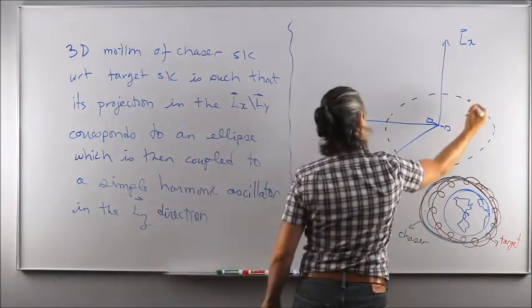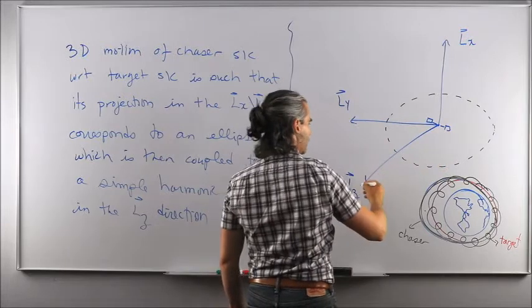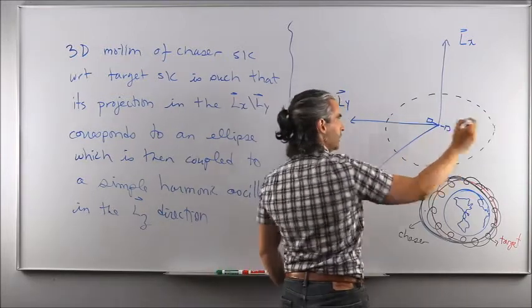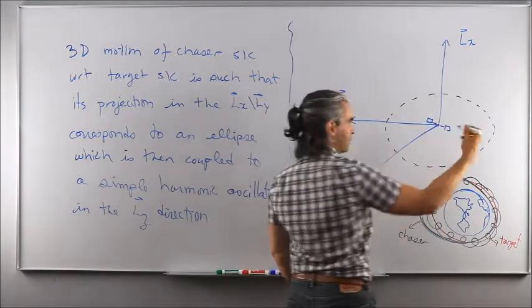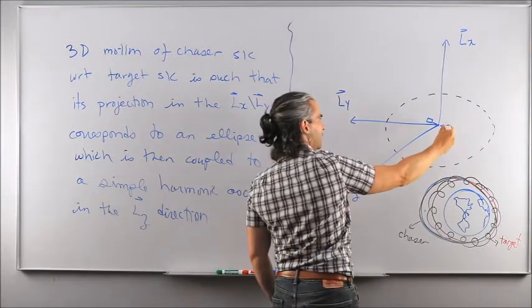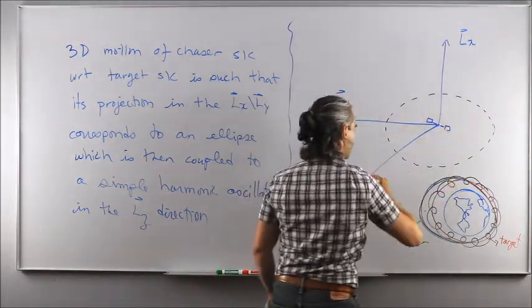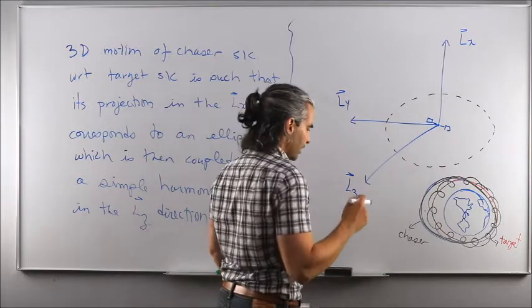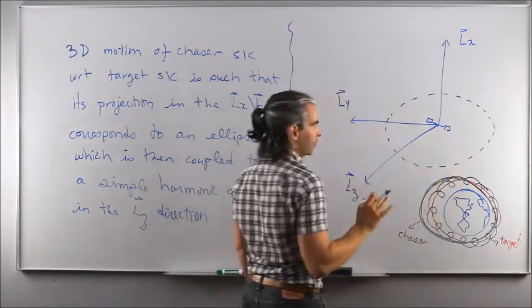And the relative motion along the normal direction to the orbital plane of the target spacecraft, so along the specific orbital angular momentum vector of the target spacecraft, essentially, right? That is the motion towards you and away from you, along this direction, LZ, and it would be just an oscillator that goes back and forth. So back and forth, towards you at the origin, past the origin, like this, okay? That would be oscillatory motion along this direction. So essentially, it just draws a three-dimensional ellipse over time. That's what it would look like, okay?